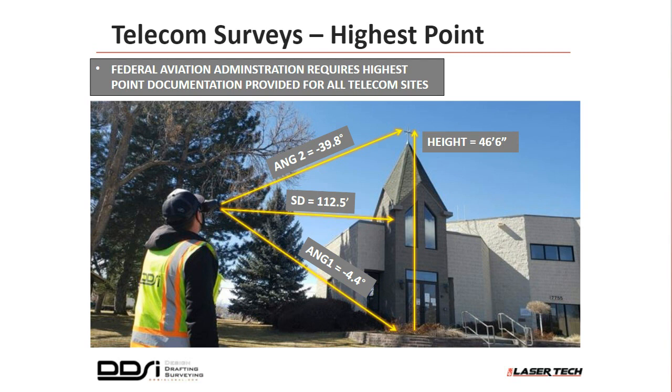And then, once again, we just add this information directly into the app that we're collecting the data with, or we'll add it to our field notes. Either way, we're able to capture this height, which is required by the FAA, and we need to document the highest point for all the telecom sites that we're expected to deliver.